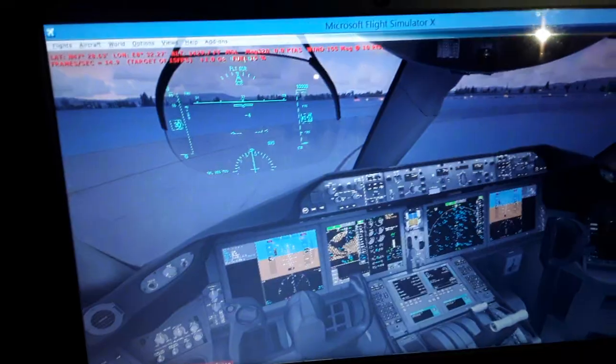The flight management computer is going to calculate before takeoff the center of gravity and the mean aerodynamic chord position, the mark where the maximum aerodynamic lift occurs on the wings before the stall begins. We need to monitor the stall. We're going to have the horizontal trim stabilizer for takeoff at about 4.35 degrees, just before takeoff. Set 15 degrees of flaps.